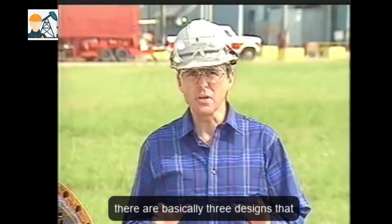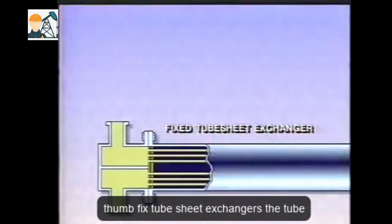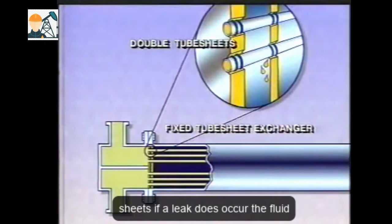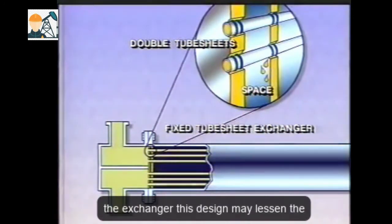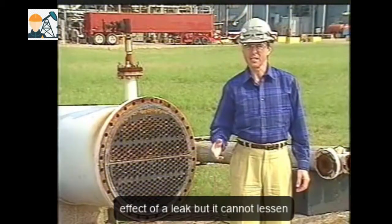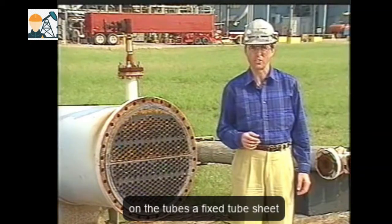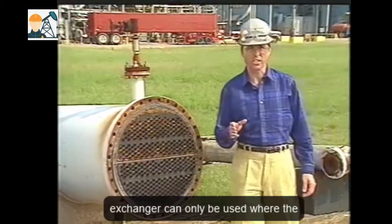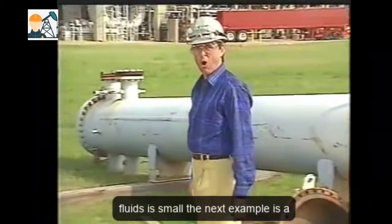There are basically 3 designs that deal with the possibility of leakage. In some fixed tube sheet exchangers, the tube bundle is anchored between double tube sheets. If a leak does occur, the fluid flows into the space between the tube sheets and can be safely drained from the exchanger. This design may lessen the effect of a leak, but it cannot lessen the stress that thermal expansion puts on the tubes. A fixed tube sheet exchanger can only be used where the temperature difference between the 2 fluids is small.